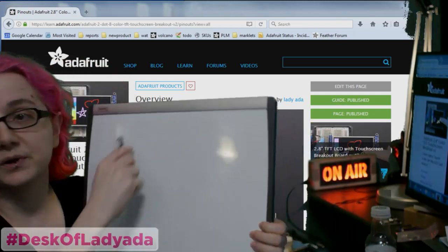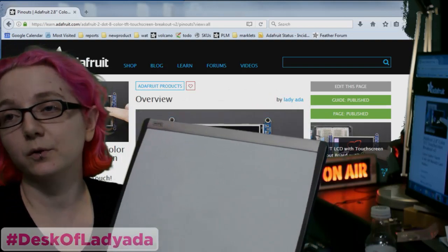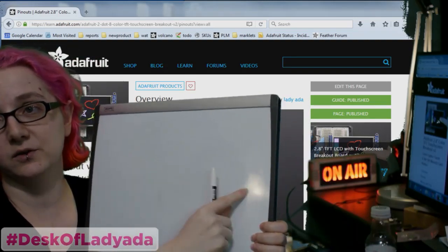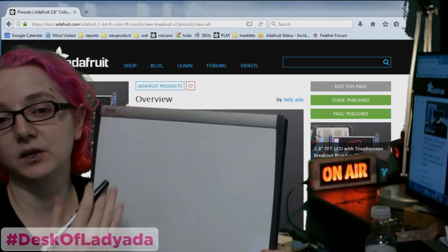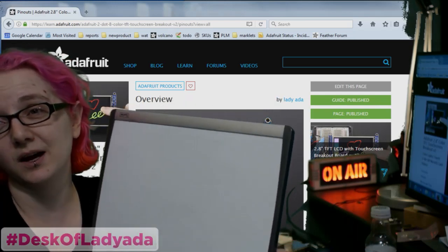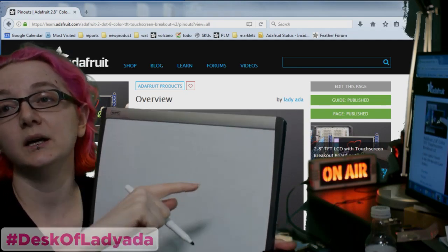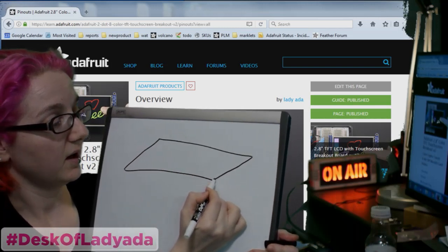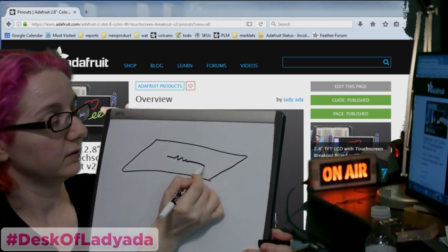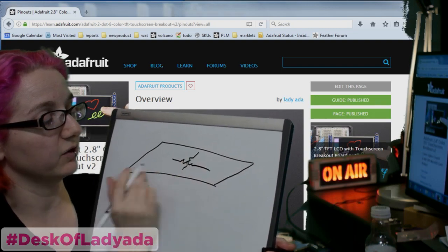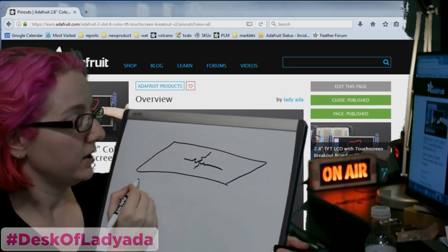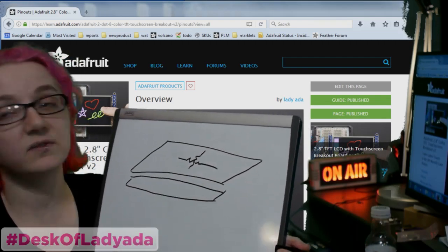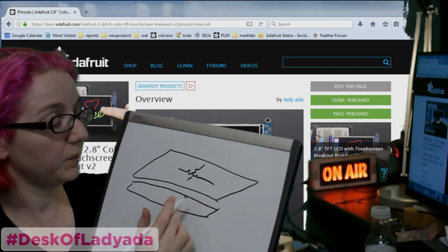Okay, so we saw the potentiometer. If you don't understand how a potentiometer works, you've got 0 volts at one end, 5 volts at the other, and as you wipe across this conductive material, you're going from 0 to 5 volts. Just imagine instead of a resistor being linear, it's a sheet. So if you have a sheet of resistive material, and it's resistive in all directions, it's a sheet resistance, and then you have another sheet right below it. This is the resistive touch screen.